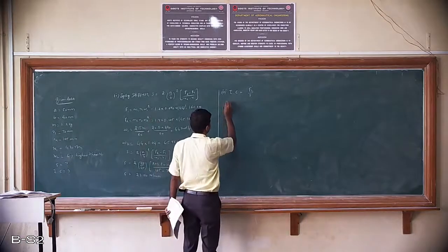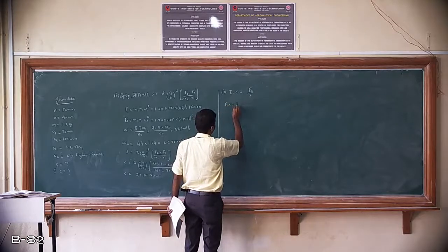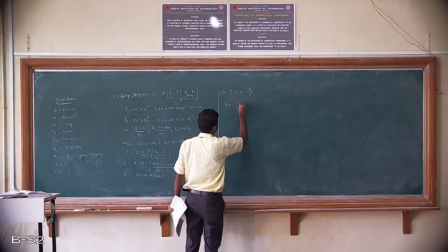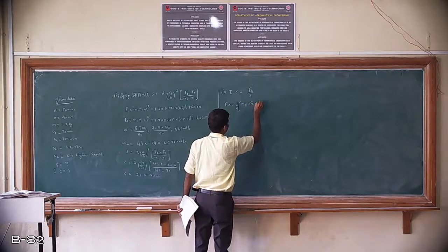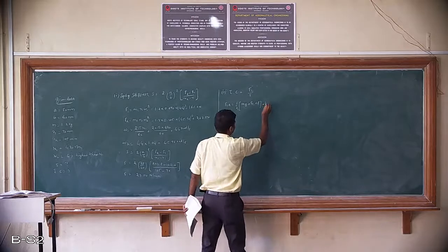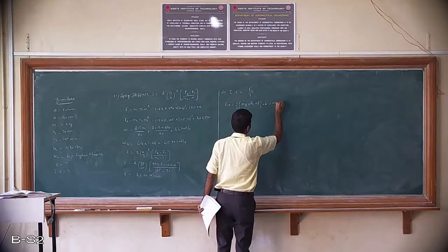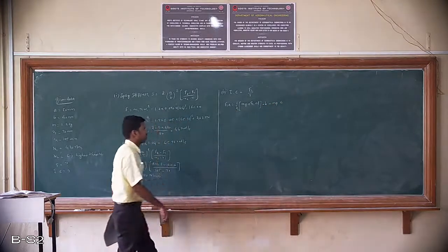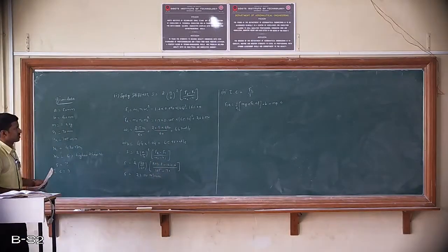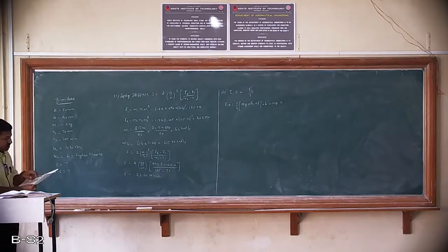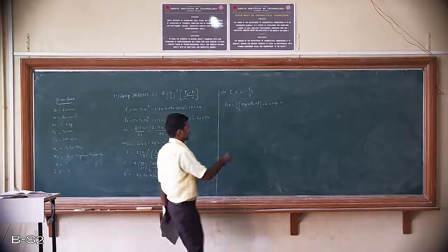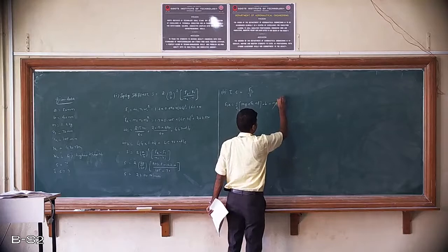We know the equation F1 into A is equal to 1 by 2 into (mg plus Fs1 plus F multiplied with B plus mg into C1). This is our equation which we have seen in the derivation of the Hartnell governor. But here the problem statement clearly says neglecting the obliquity of the arms. So if I neglect the obliquity of the arms, then this whole term becomes 0.